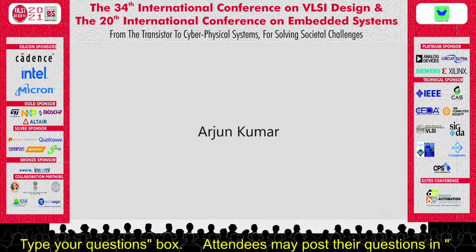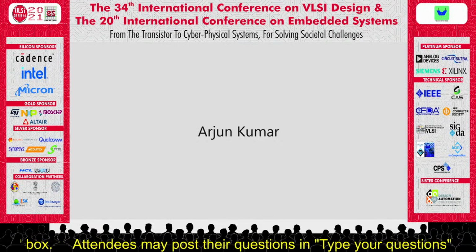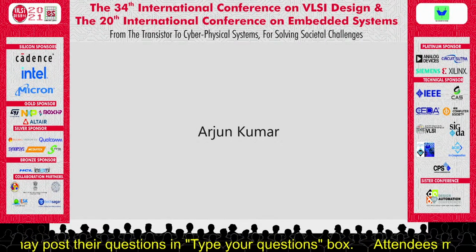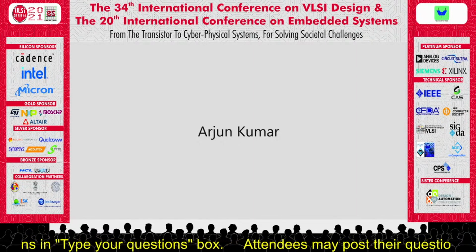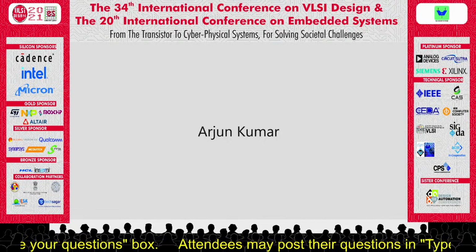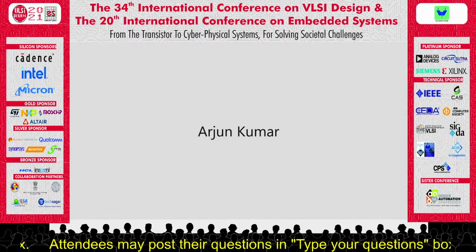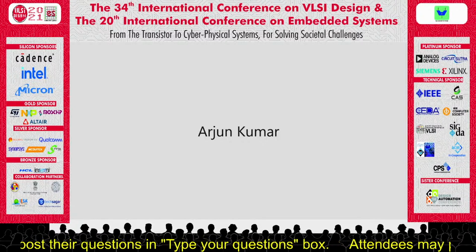It will require much more time, because right now the current MOSFET that is fabricated is around 65 nanometer. There are some studies on 1 nanometer, but contact resistance plays a huge role in getting the best performance. So it may require more effort. CVD is one approach that can be used to produce high quality MoS2.